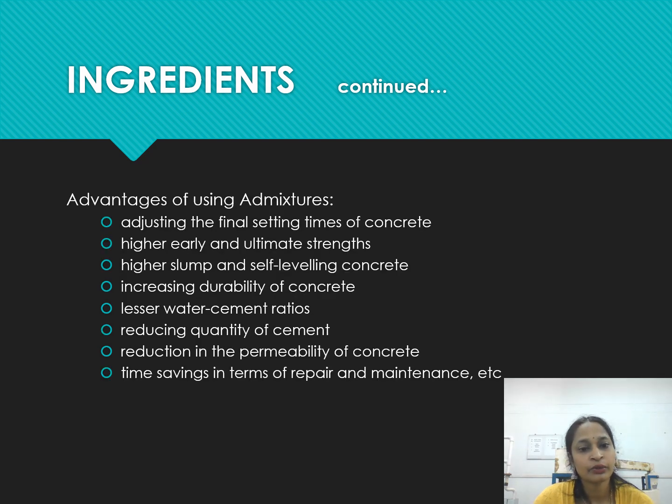Coming to the advantages of using these admixtures: adjusting the final setting time of concrete, higher early and ultimate strengths, higher slump and self-leveling concrete, increasing durability of concrete, lower water cement ratios, reducing the quantity of cement, reduction in the permeability of the concrete, and time saving in terms of repair and maintenance.